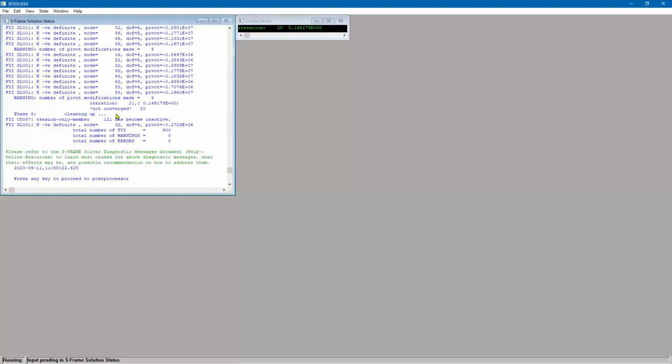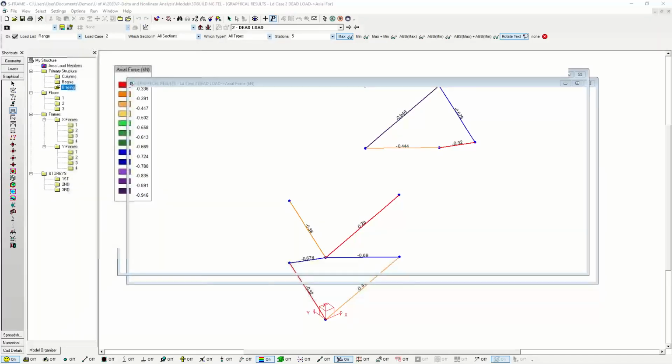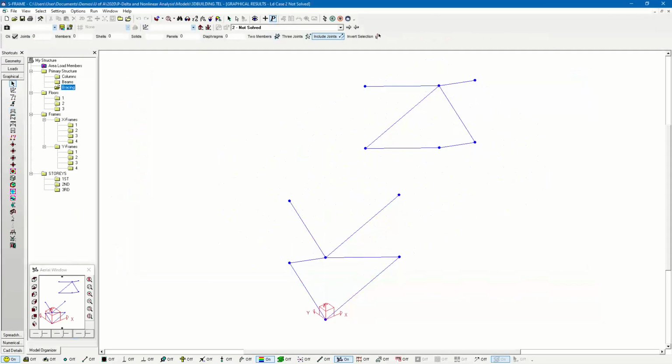We had some issues with stability. And this is one of the downsides of going with a nonlinear analysis, is that it's a little bit unforgiving with unrealistic loading scenarios. We have to consider the fact that having purely axial or gravity loads isn't really a realistic scenario in the real world. We would probably have some sort of imperfections in the model, maybe some lack of plumbness or some sort of geometric imperfections that would be inducing lateral loads. And so we're not able to look at these results because with just those gravity loads, these are found to be in compression and they're actually required for stability in the model.